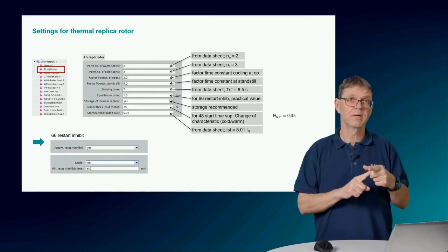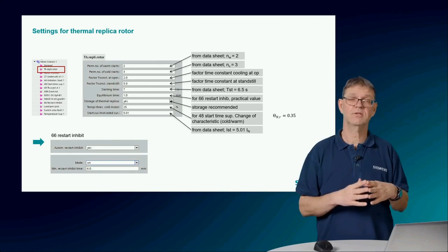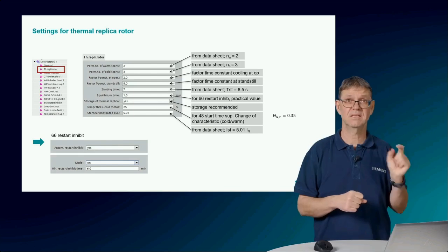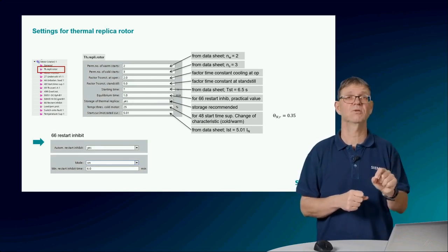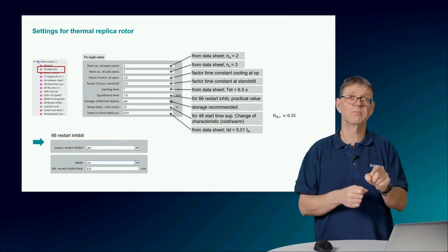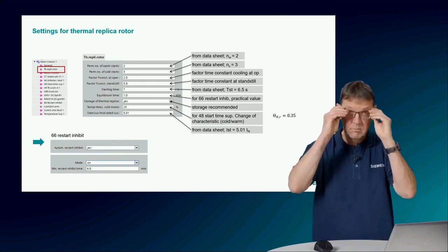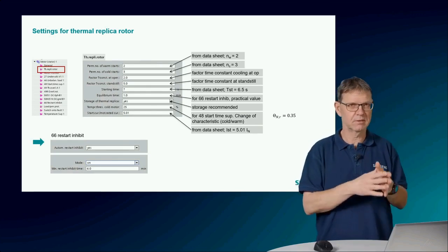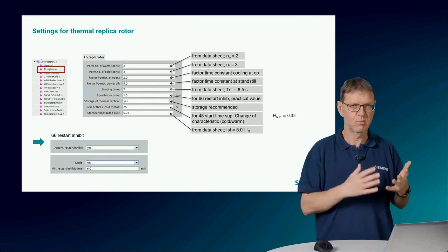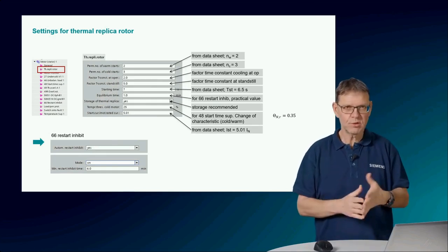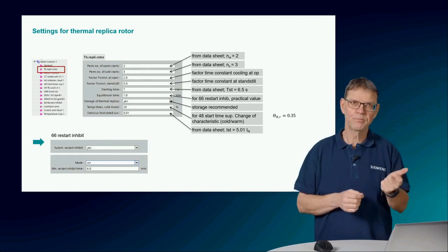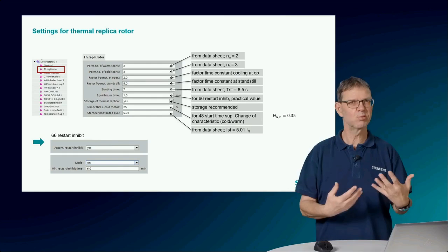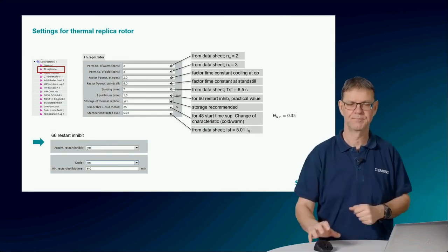Automatic means if we use the internal control function of the SIPROTEC 5, it prevents the closing command and keeps the tripping command. So you open the motor, and at that moment it trips the motor basically. If you don't want that behavior, you set this to no. That means you have just a restart inhibit signal, and you can use this signal to block the reclosing externally.